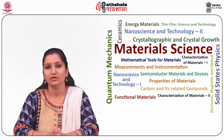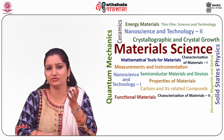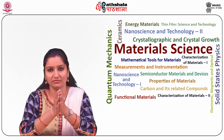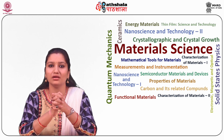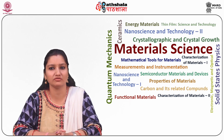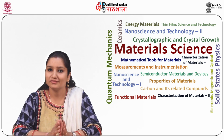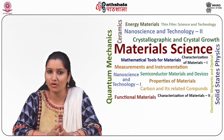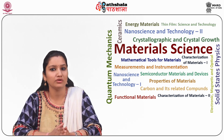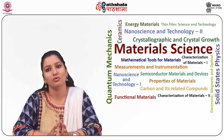The bombardment often leads to an increase in density of the film and helps to remove contamination, thus improving the film's electrical and mechanical properties. When high density plasma is used, the ion density is high enough such that significant sputtering of the deposited film occurs. This sputtering can be used to help in making the film planar and fill troughs or holes.